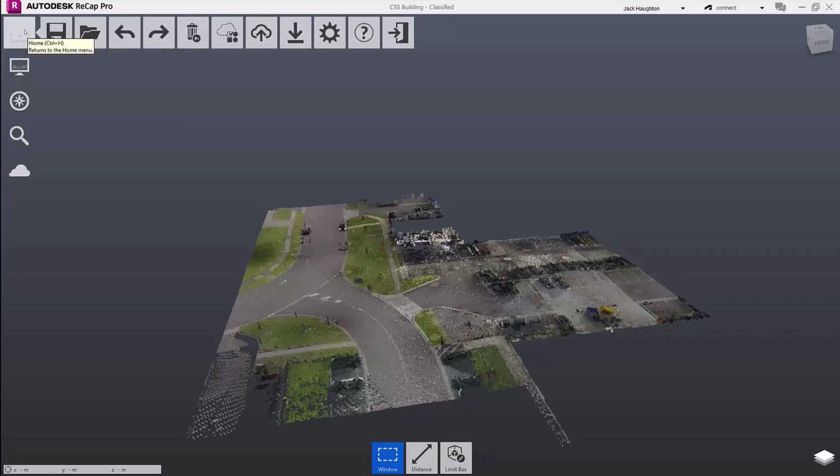From there, you pretty much just go ahead and fiddle with it until you get something that you like, and you're ready to export the data that you wish to work with. And the way you go about exporting, there are two ways to do so. If you're planning to work more with the building side of things, so this is getting your internal walls, working with the architectural side of things and all that, I recommend running the publish command. Publish will push it out to your Autodesk cloud and will allow you to run the ReCap version on the Autodesk cloud,